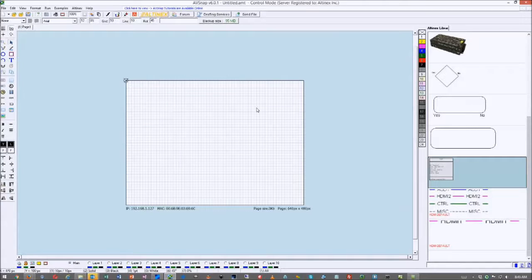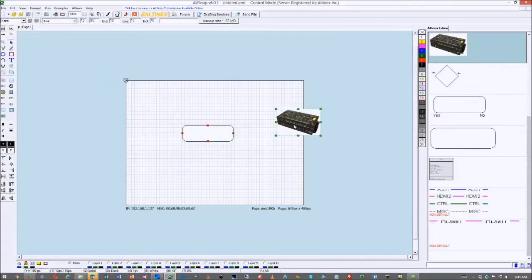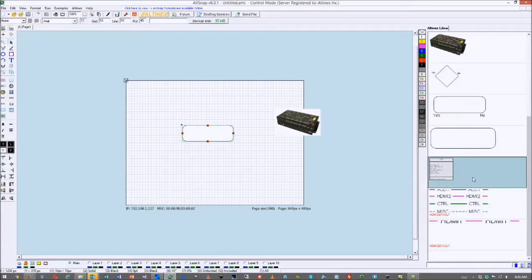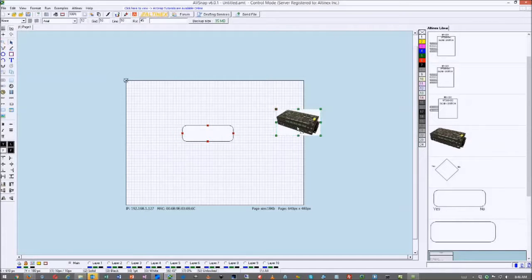So we've covered most of the symbols that are available. The rest of the symbols, if you go, for example, here, the rest of the symbol types, okay, metric, outline, they're pretty much the same as a diagram, but it just gives you ability to sort them. So if you have multiple types of symbols in the library, then you can actually sort it by symbol type. Now, personally, I like to create different libraries for different symbol types. I try not to mix them in the same library. Now, a couple of other things, and we'll move on in managing the libraries.